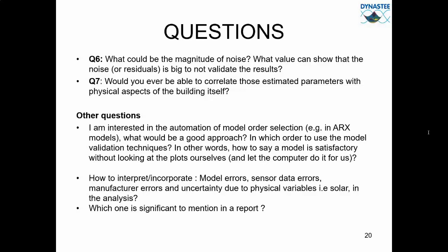I don't know if you can all open that right now on your computer, but on page 31 there's a suggested model validation procedure, which also includes model selection. The basic idea is to use the first order ARX model and then increase the order, so include more and more lags until you obtain white noise residuals and until the p-value of the coefficient estimates, whether they are significantly different from 0, is too high, usually about 5%.